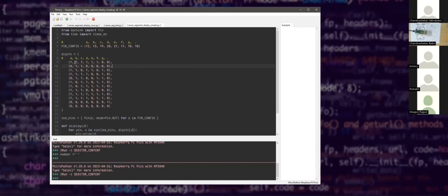So if you want to represent one number, what displays must be on? I think it's for 0. For 0, you need to turn on all the surrounding LEDs. I think this is a layout, right? We can see that right here. So we can see the surrounding layout. We can say A, B, C, D, E, F must be on for 0.